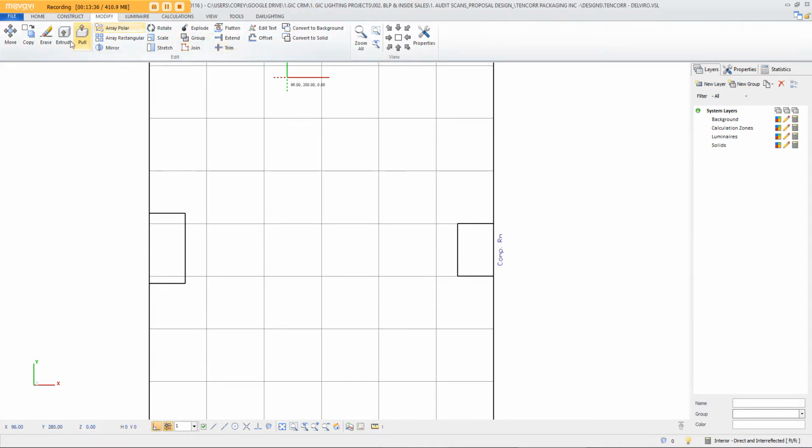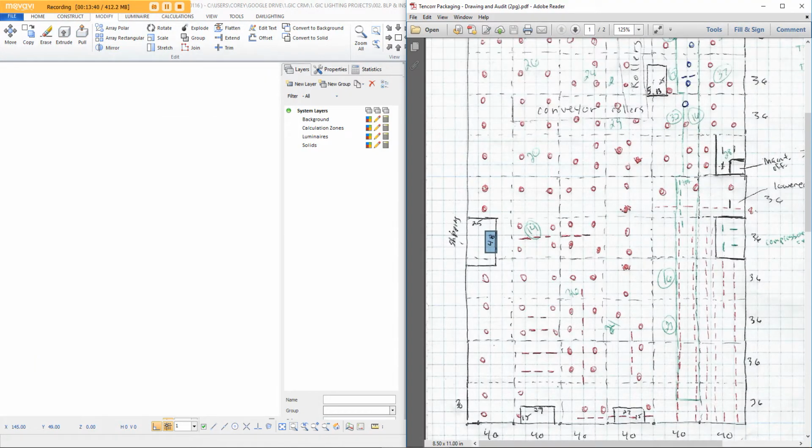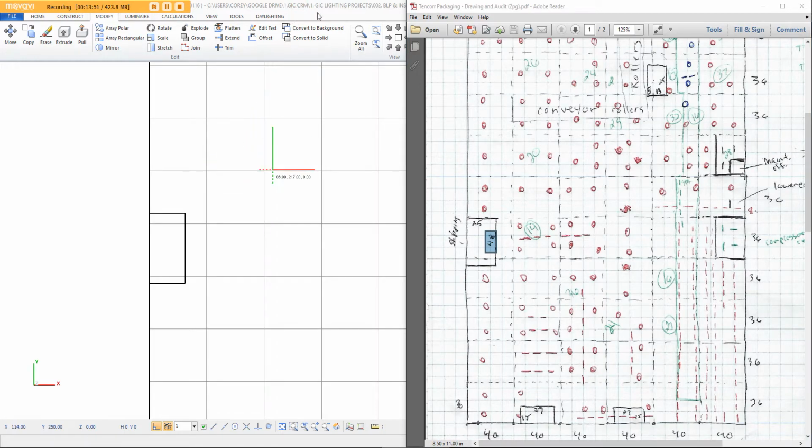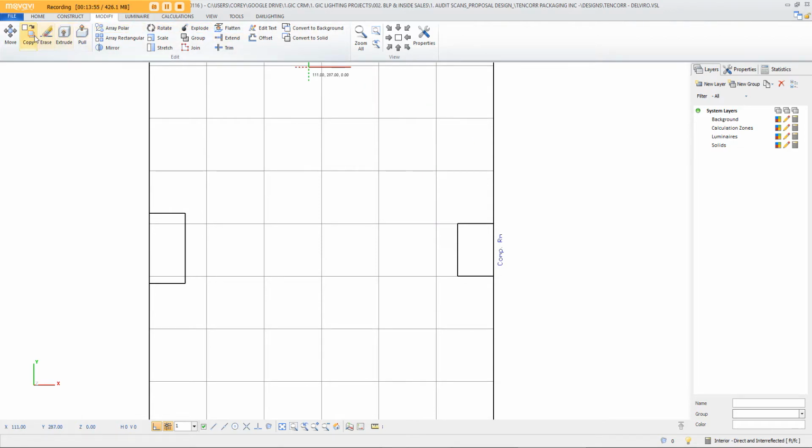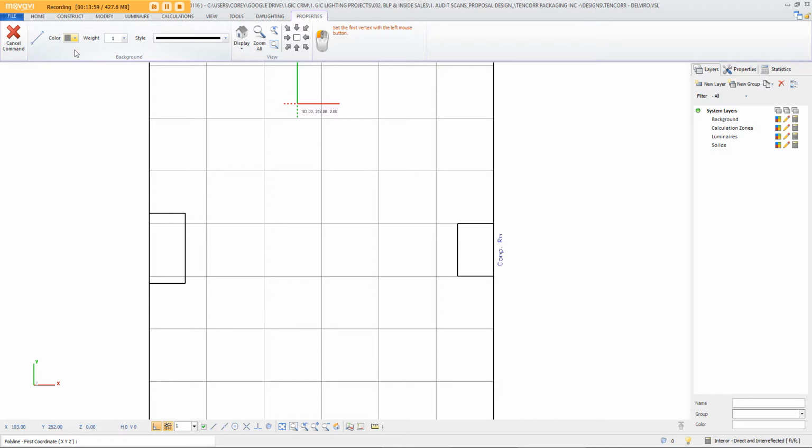Next spot, what we're going to do here is notice that the maintenance office is just a solid line. It's one small office in the center. This is not actually a closed room here, it's just a wall. So if I go back to maintenance room, or to Visual, I'm going to get my line drawing out, so I just press L. I'm going to go with a solid dark line here, and I'm going to bring it over.